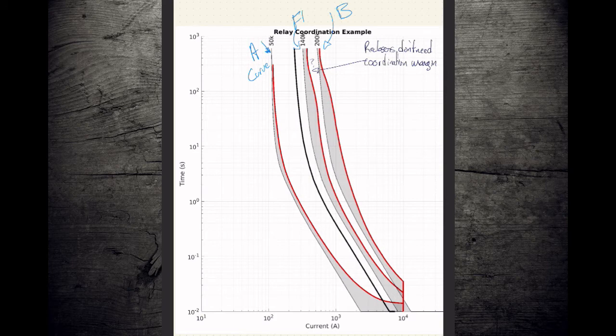And that makes sense when you think about it because it's a computer. It's going to behave exactly the same. Computers don't care if they're hot or cold. Computers don't care if you run them near their limits or way below their limits. That doesn't bother them at all. There's nothing here that's getting hot, right? There's no preloading effect. We've got instrument transformers. They're designed for that. They really don't care if they're run at their operating ratings or not. Their output is going to be exactly the same.